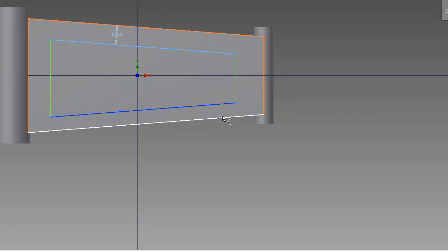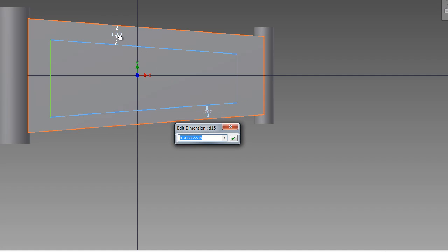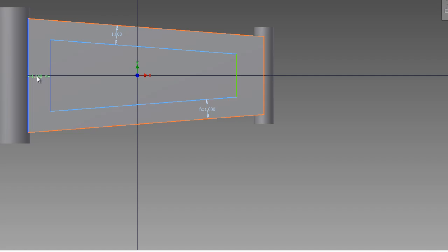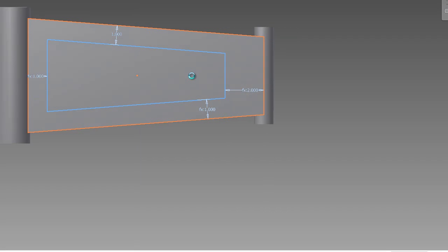The reason why this is nice is because that can be used later when you're doing something like an iPart, iAssembly, anything like that. You're going to notice here as I'm adding these dimensions, I can actually just type in the word offset. I can select the other dimension, or I can type in the word offset and use something as, let's say, times by 2, again letting the computer do the calculations for me.